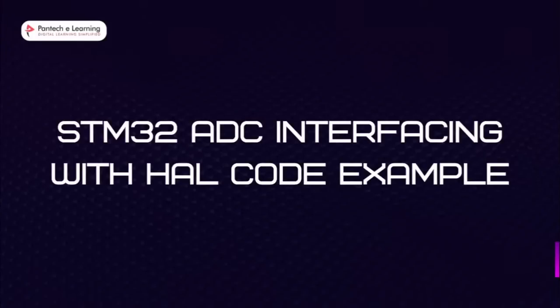output in PuTTY software. Okay, so the STM32 microcontroller is a 32-bit ARM Cortex-M based microprocessor that's commonly used in embedded system applications. You already know that, right? The STM32 has a built-in ADC peripheral that allows it to interface with analog signals. The ADC module in the STM32 microcontroller can convert analog signals into digital signals with varying resolution, from 12 bits to 16 bits, which totally depends on the microcontroller and its features.